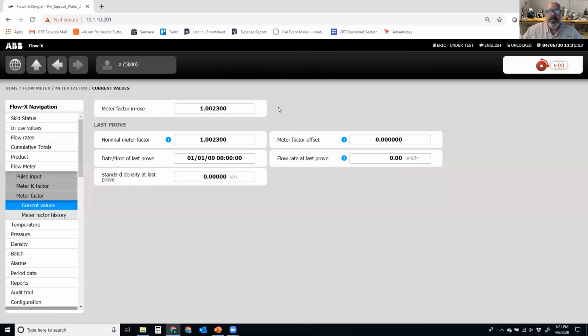We're not getting into how we're calibrating the actual instruments. We're going to do a couple of short videos on how to do temperature calibration and pressure calibration. And when we make the changes to be able to do as founds and as lefts for process inputs, we'll create another video where we can demonstrate how that's done within the FlowX. So are there any questions on the analog input or analog output or RTD calibrations?